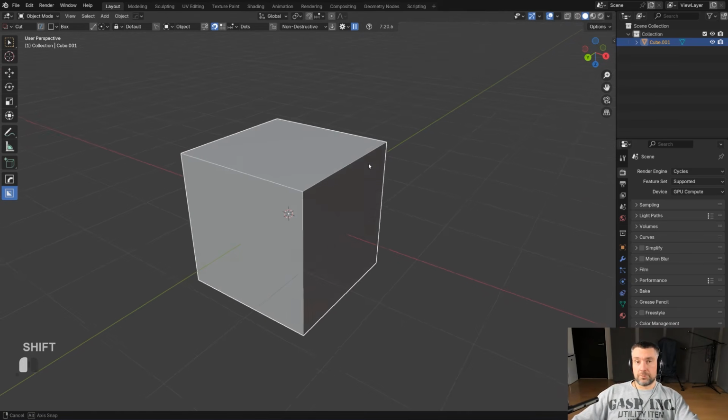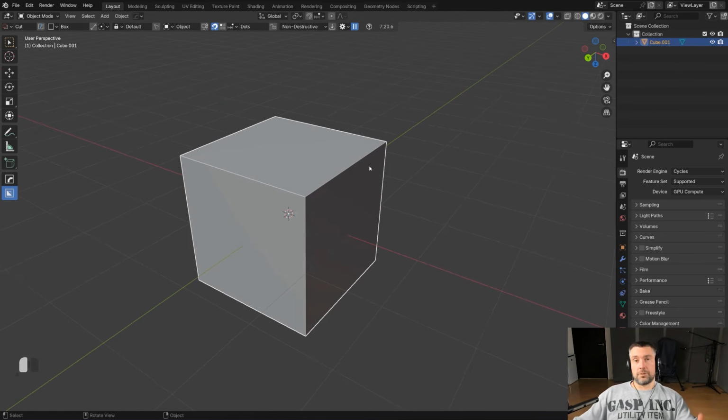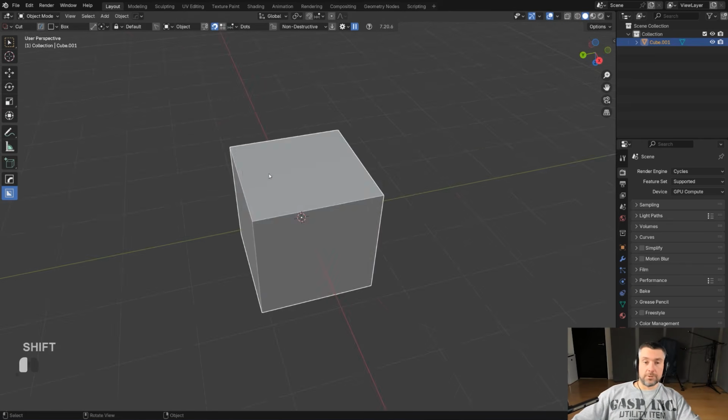In addition to this one, you don't need bevels, and we know that if you're going to have a lot of booleans in your scene, and they're live booleans, which means you don't apply them, you keep them on your mesh, you have a lot of models, a lot of objects. In addition, you got bevel on top of this, your UI is going to slow down. So cavity is kind of like a fake bevel, sort of like the bevel baking, remember, with our add-on Materialworks. That's going to allow you to see that edge much better and simply create better models.